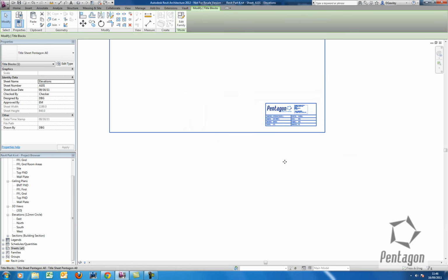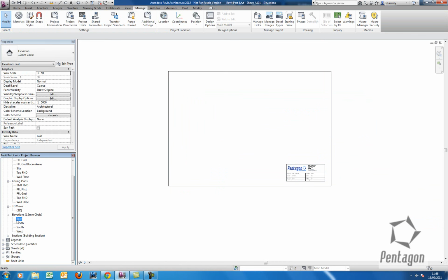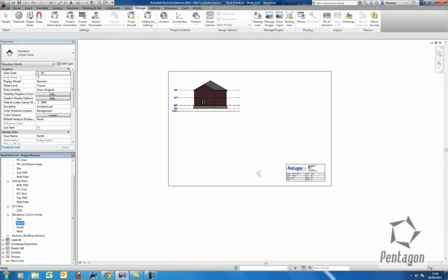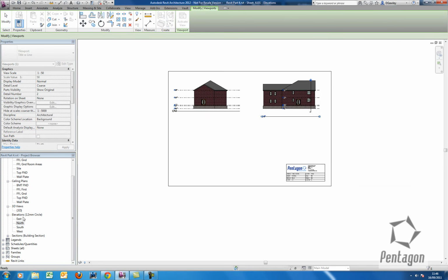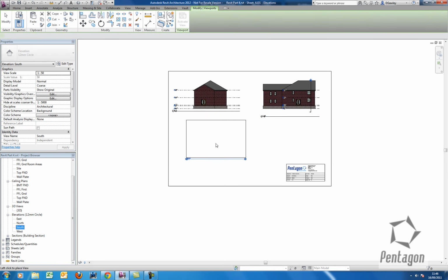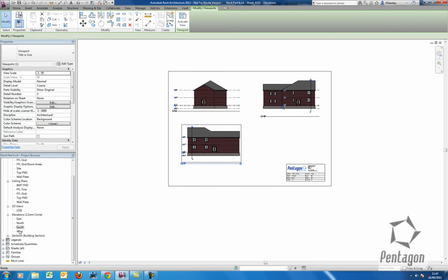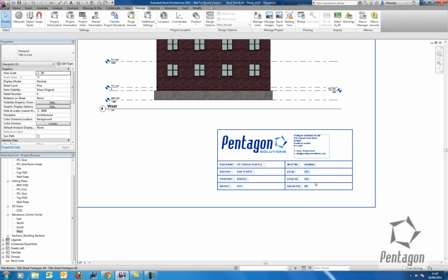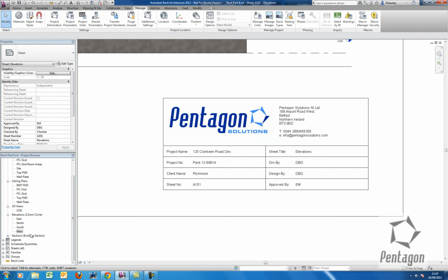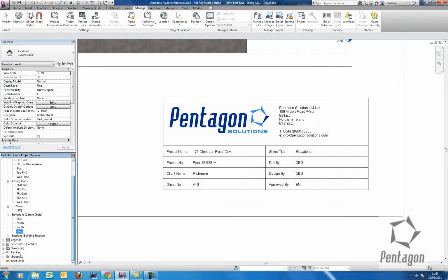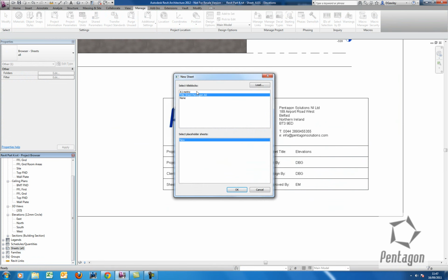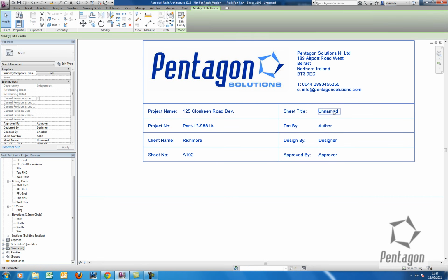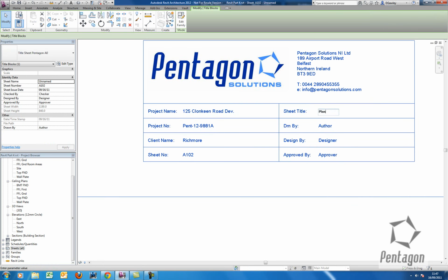and what I'm just going to do is simply test it. I'm going to drag and drop in my elevations. Let's populate these in. My east, my north, again my south, and if I can fit it in, my west. So again, I've got my new title sheet. I've got my title sheet ready to go. If I create any new sheet based on that, if I create another new sheet, you'll see that it fills in the project information, but it goes to a different sheet title, and that's quite important.